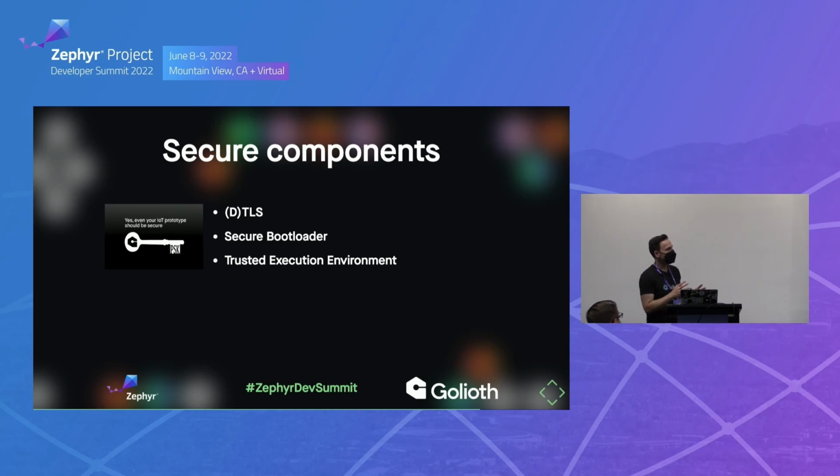And there's even some aspects of trusted execution environments. Has anyone heard of a TEE or familiar with this? So it's a secure enclave. It's making its way more and more into IoT applications. It comes more from the server world and now getting to the tiny device. If you're talking securely to a service, you might have some sensitive data. Well, do you want to run it in your main thread on your main application, or do you want to put it somewhere more safe? And that's what a trusted execution environment is good for. And there is support in Zephyr already.